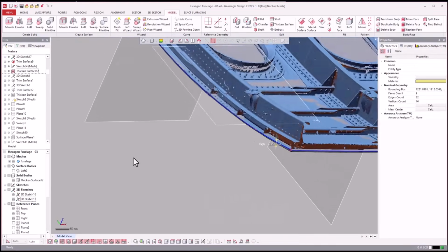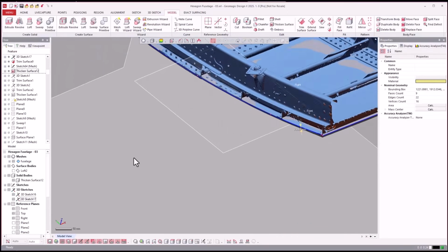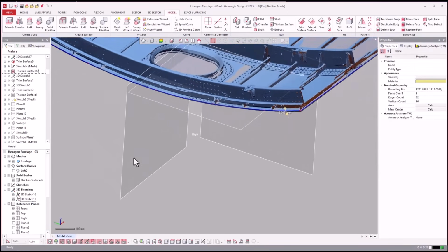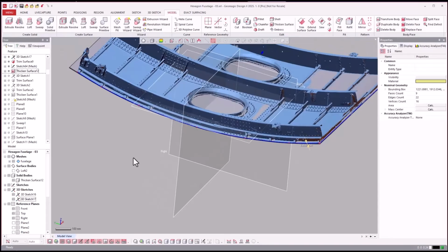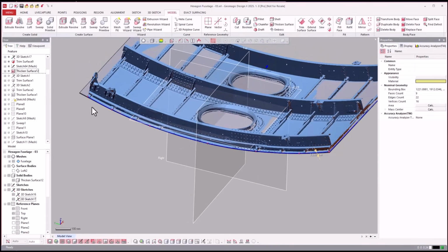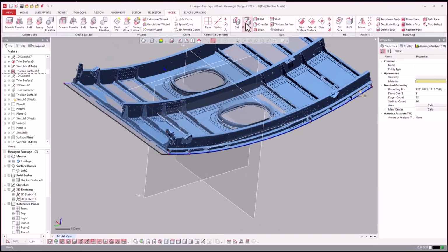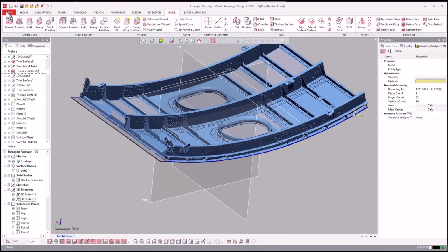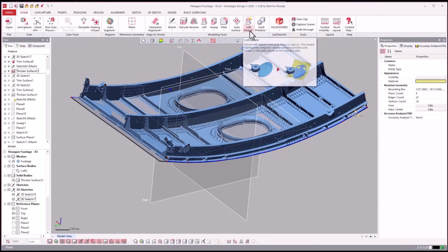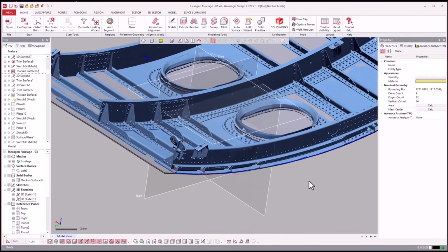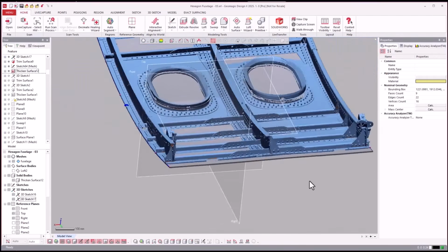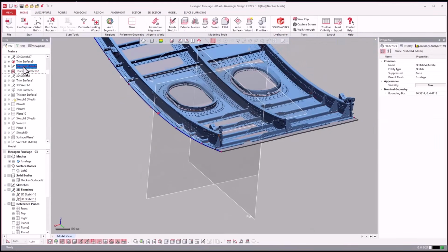So I could have modeled it this way by just drawing the 3D sketch instead of a mesh 3D sketch to create my boundary surface as well, to create this guy that we thickened instead of using the loft wizard here. And then using dimensional sketches. So now we'll go ahead and just get rid of that and just keep rolling forward.